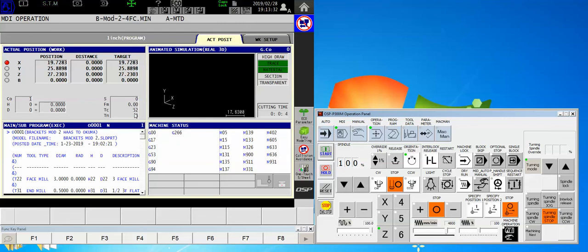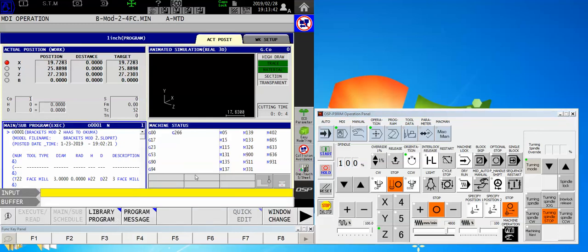I can now bring it down, touch it off of the tool setter, or I can manually input the tool data, touch it off the face of the part, whatever your prescribed method of tool offset acquisition is, and I can rock on. I just will not see a three-dimensional representation of the tool up here in the window.